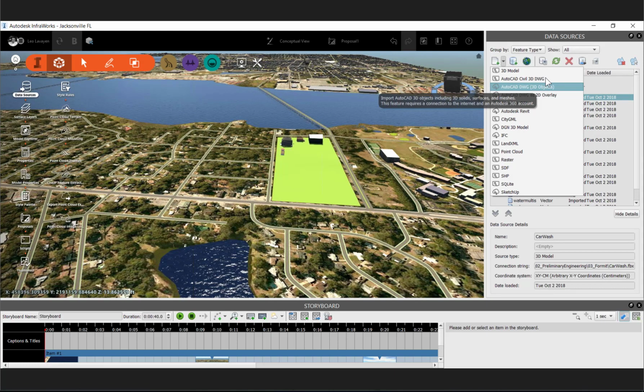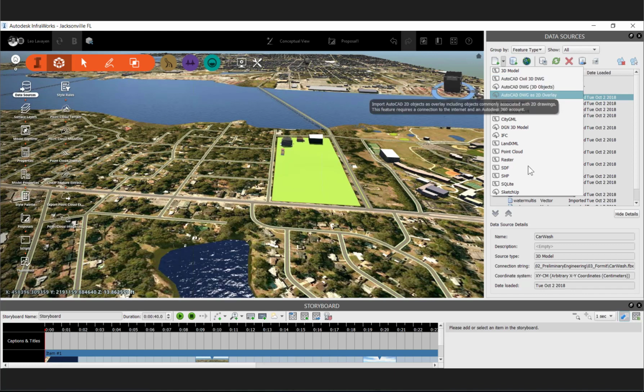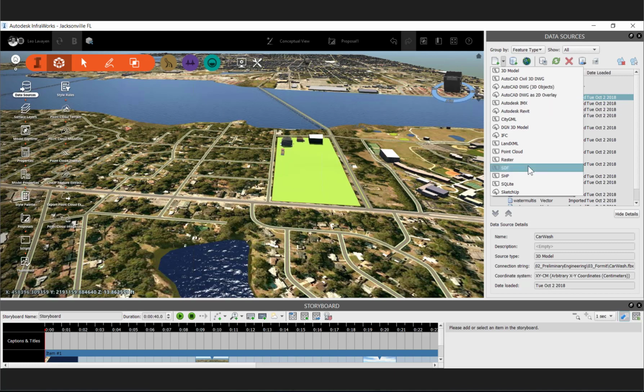Now there is an option to do an overlay, and overlay is basically an XREF. If you have actual line work geometry that represents a paved area or a site or elements, the only way I know how to do it as of right now is leveraging SDF. From your AutoCAD or Map session, push out SDF elements and bring those SDF line work elements inside of InfraWorks. I can easily bring in Civil 3D, but bringing in AutoCAD would be a workflow through SDF. Just wanted to let you know.